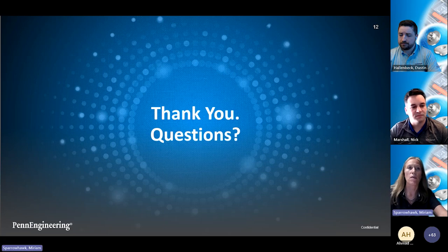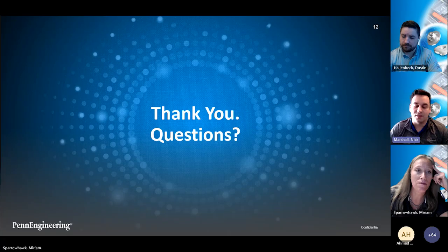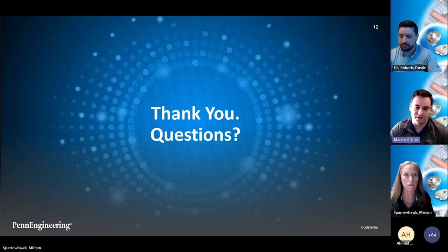Okay, great. Nick, could you answer the question about how the eConnect contact bushing's electrical resistance compares to welded bus bars? That would very much depend on the specific welding that we're talking about. There's a great number of welding options that are being used in the industry right now. There is ultrasonic welding, resistance welding, friction welding, and each of them has a different resistance value corresponding to it. In general, we find that our resistance values are on the low end of what you'll find with welding and are more consistent from joint to joint.